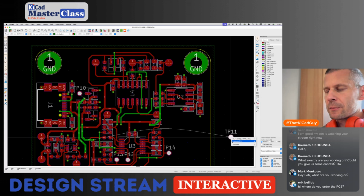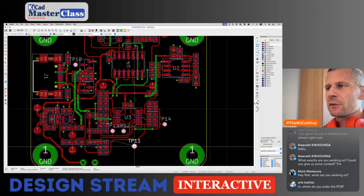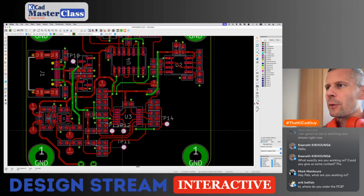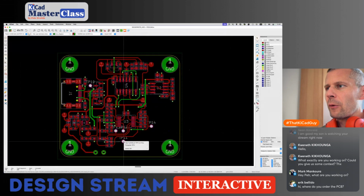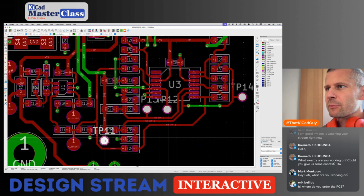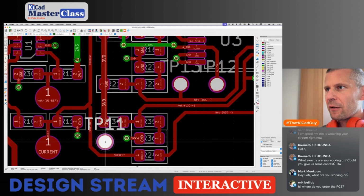Now I'm placing the test points. I added some functional test points inside of the circuit, which were already placed, and now I'm placing the reference voltage test points just for the brief check when powering up the board.